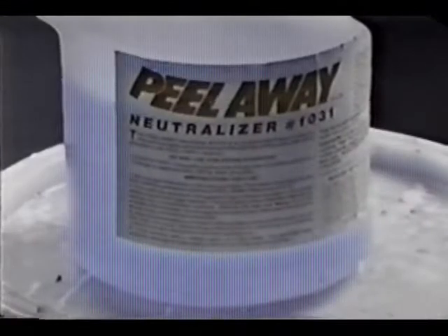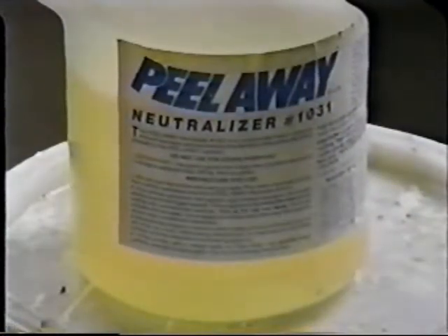Be sure to scrape any residual paste or paint left on the surface promptly. All scraping needs to be done while the surface is still moist to avoid dust generation. The stripped surface is then thoroughly washed down with solution. The solution usually contains an acid. The solution neutralizes the surface and prepares it for repainting.